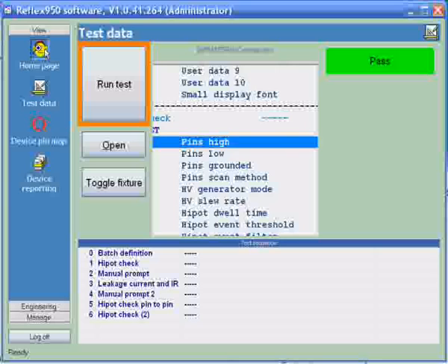So here we tested 3 pins relative to 1 pin, but there are situations where we want to be able to test banks of pins relative to one another. For example, we may have special components fitted here from this row, pins 150 to 155, to an adjacent row 142 to 147. So if we specify those pins